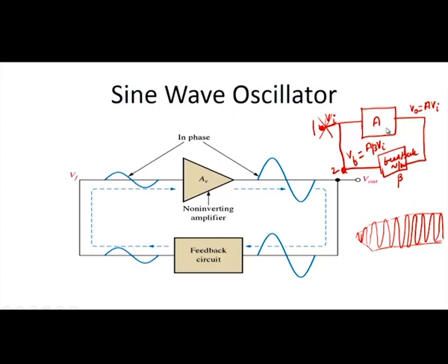This amplifier is actually made up of a transistor, and due to its non-linear characteristics the transistor will go to a saturation level, and the amplitude of the oscillation will also get saturated. Even though it is an amplifier, at one time it goes to a saturation mode, and then the oscillation will also get saturated.